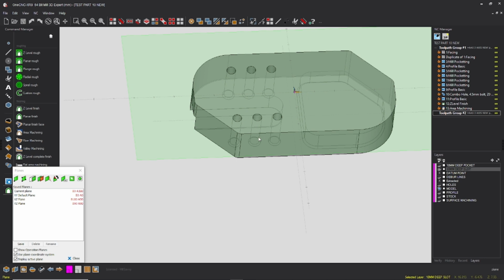If you're a little bit out, all you're going to see is you're going to gouge in with your chamfer on the back face, and you'll scrap the part. So don't assume anything. Come in and double check it. Do it the same every time, and you're going to get a good result every time. So let's save that now. We'll call that G55 plane.